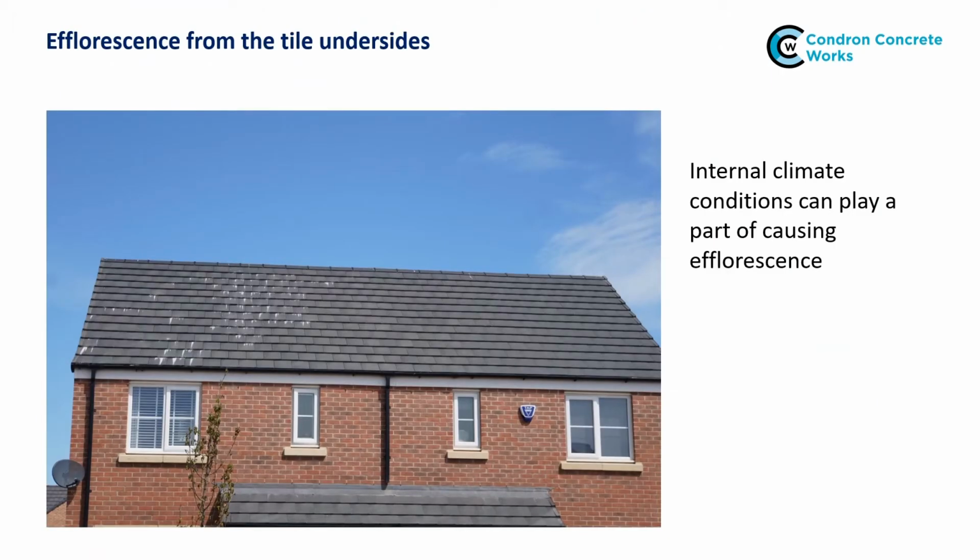The internal climate of the building also plays a part. See here how the efflorescence is only on one side of a pair of semis, even though the roof tiles came from the same batch and were installed at the same times, perhaps indicating that there is more moisture being generated by the occupants in the left-hand house.